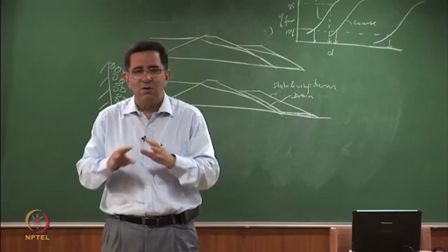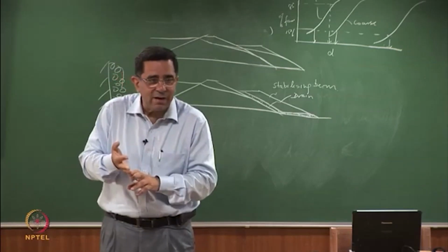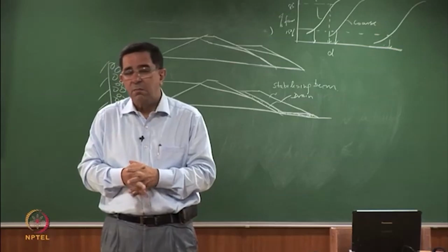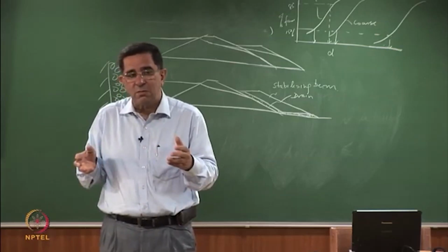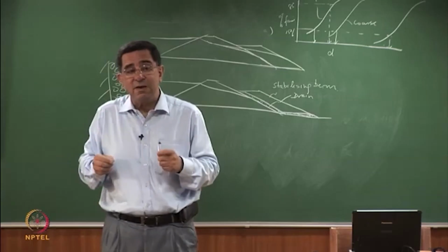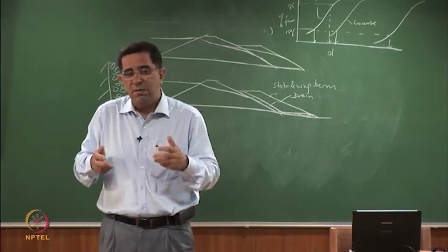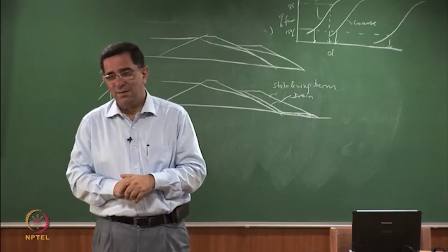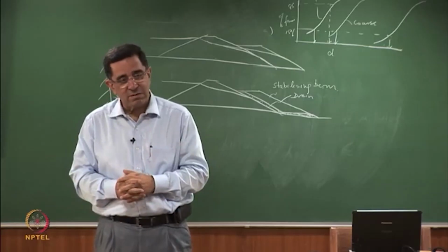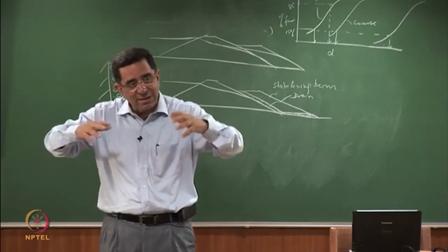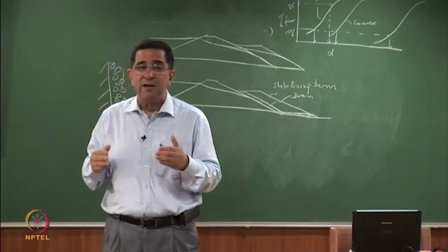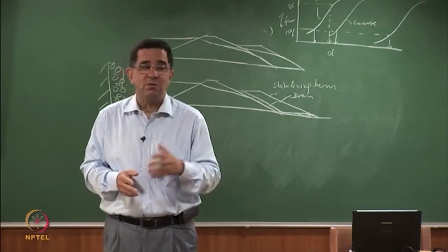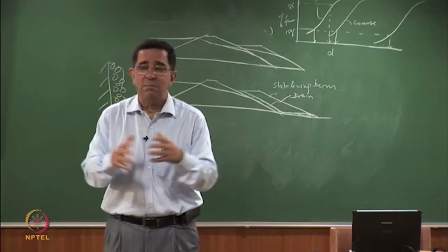So these are flexible elements. There are no limits on the settlement due to cracking or due to any other factors in this. Intuitively one feels that in slurry deposited waste there will be a lot of settlements. If it is time dependent settlement, suppose you have very high fines, then you are in trouble. Why? Because after you have made the embankment, if you get 10, 20, 30 centimeters of settlement, then there is gradually sinking. But both in ash ponds and in mine tailings ponds, drainage is pretty quick and you don't get time dependent settlements which are that significant. Most of the settlements take place while the embankment are being constructed.